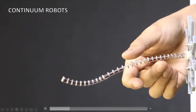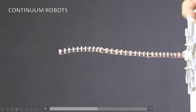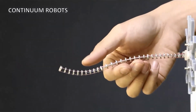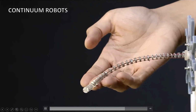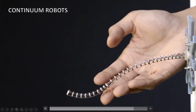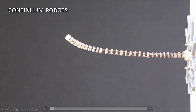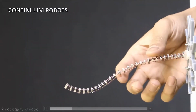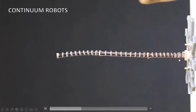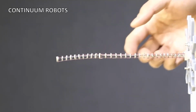And one main characteristic of these robots is that I don't have any joints within my structure itself, but all the actuation is actually outside of this robot. We also talk about extrinsic actuation. So in this specific example, I have a couple of tendons that are routed along this flexible structure, which we also call the backbone. And then all my actuators and motors are outside of the robot, and they are pulling these tendons, leading to an actuation of this robot in bending. And since I don't have any joints in my structure, that allows me to build these robots at very small sizes and form factors, and I can easily miniaturize them.